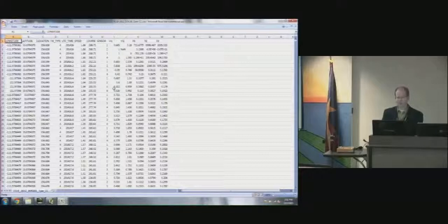So the first output for a crop circle would be a vegetation index, and the second one is a different vegetation index, and then we have the R1, 2, and 3, which are the raw reflectance values for a 3-band crop circle instrument. The sensor column, as I mentioned this morning, is the column that tells us which crop circle sensor is being recorded on that particular line, because we have 4 total crop circles on the tractor, and so you need an identifier to tell which crop circle instrument is being written out on a given line.